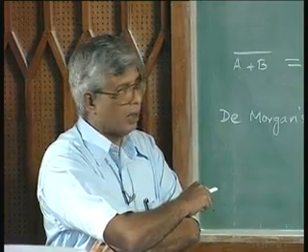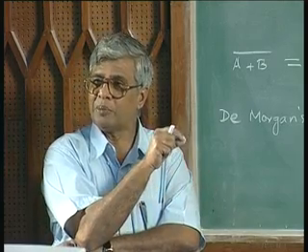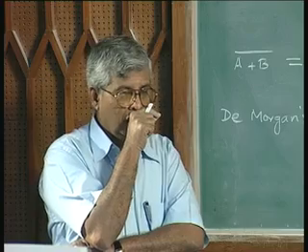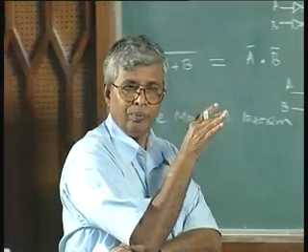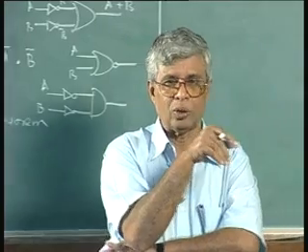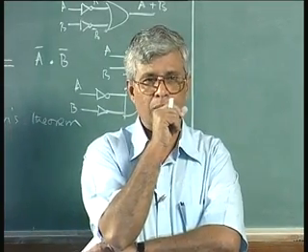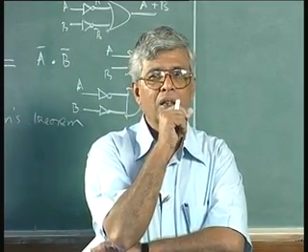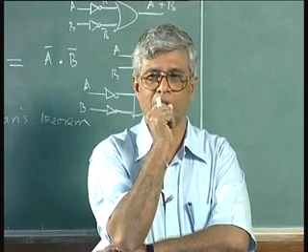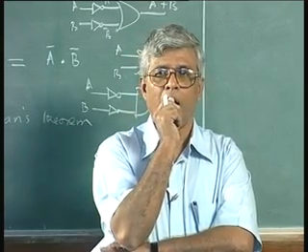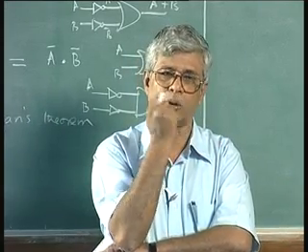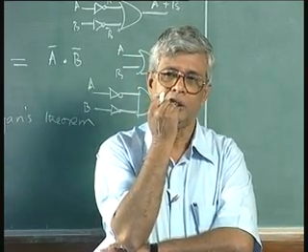So, if you are not clear about that f is equal to A plus B bar, B C bar, that is the original function we talked about, you are only given the truth table, you are only given the minterms for which the output is true, 5 minterms for which the output is true, the original truth table or the canonical sum of products expression in terms of minterms. There is another way of approaching, because there are 5 terms for which the output is true, I want to simplify it to a minimum number.